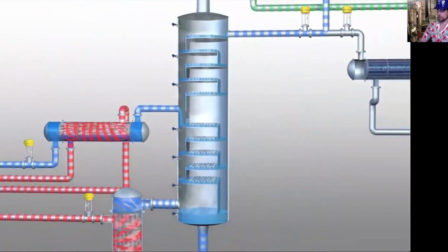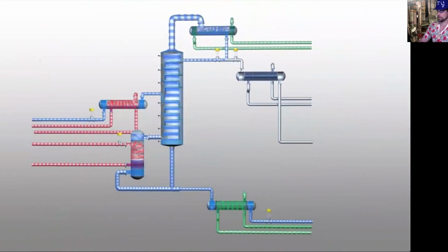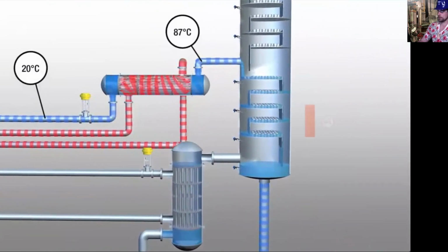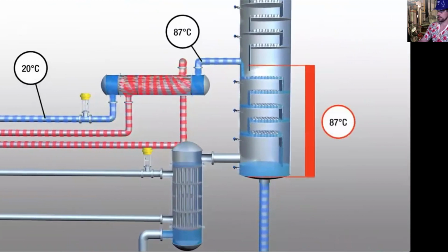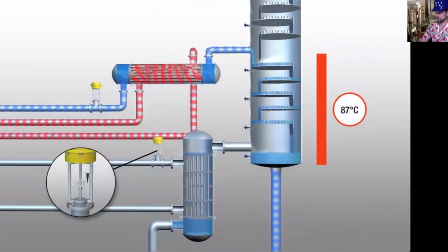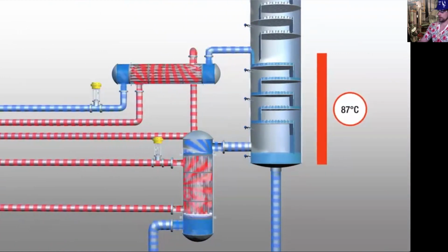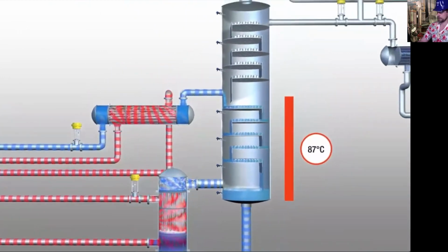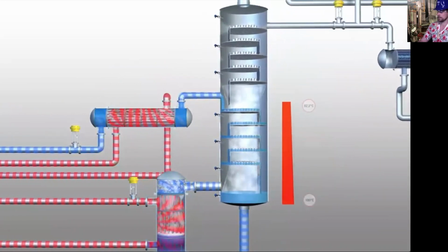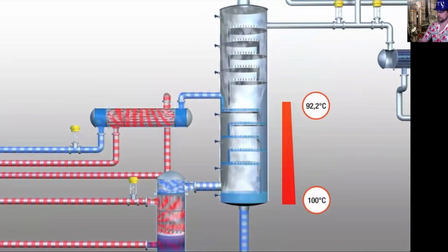And so where we have that first heat exchanger there, heating our feed to a desired temperature, you can see the full flow there. You have an initial temperature and then your feed temperature. And so that sets the very initial temperature profile of your lower column. And then as energy is added through the reboiler and that lighter component is vaporized, as that hot vapor enters your column, you can see that it's going to change the temperature distribution of that lower part. And it'll also, you can see, affect the upper part.